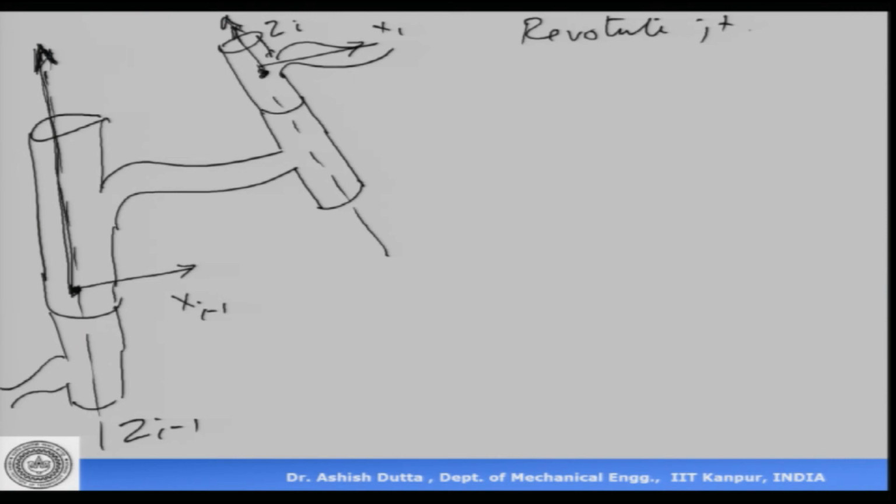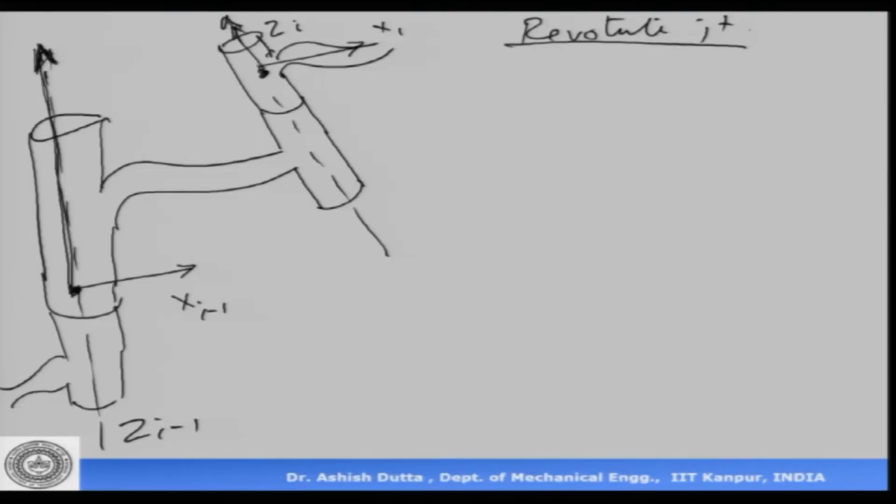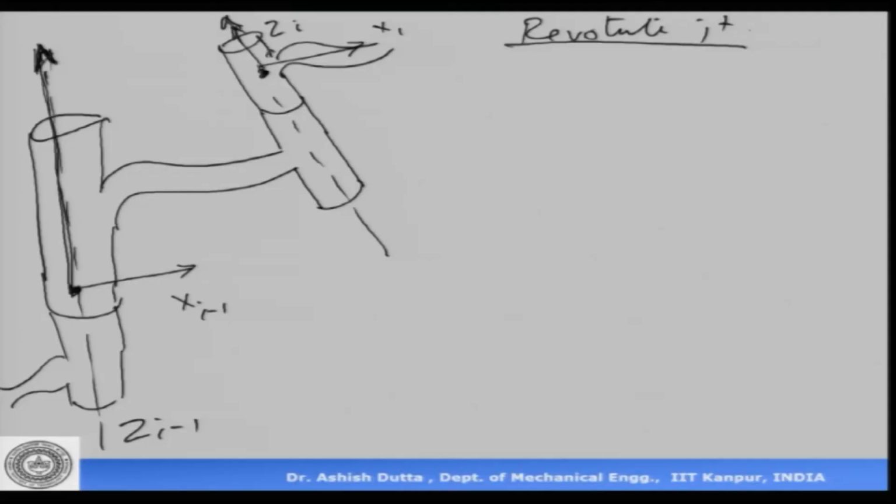We have seen that essentially you have two kinds of transformations, rotations and translations in space. But if you are going from one frame to another frame in space, then what is the minimum number of rotations and translations that you require to go from one frame to another? That is what DH parameters are useful for, because it gives us the minimum number of transformations required. Now if you have more transformations, you will have more multiplications. So the minimum number is the best, because there is no point in having more transformation matrices, your complexity increases. So how is this done?